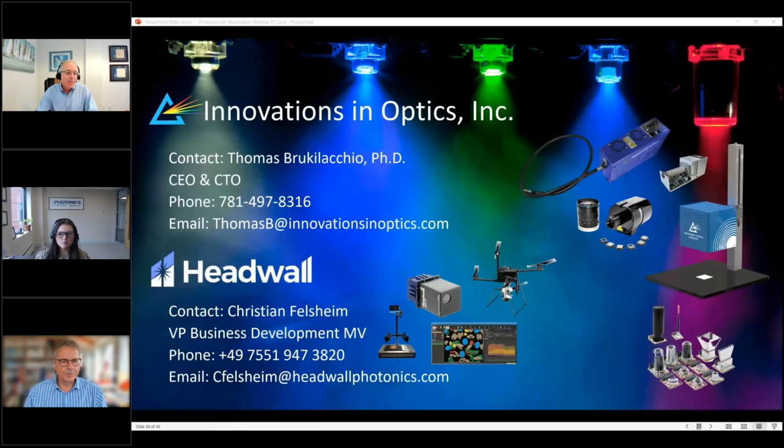Yeah, I couldn't agree more with what Thomas said. That was the reason why in the past halogen illumination had been so popular for hyperspectral imaging, because it has a very uniform spectrum in the width as well as in the depth. But with LEDs, this has become more complex, so you really need to keep an eye on that. And that is also about when you analyze the data. If your analysis algorithms depend on where you measure and which depth or which width, then this costs you speed. And that's not what you want to have, definitely not.